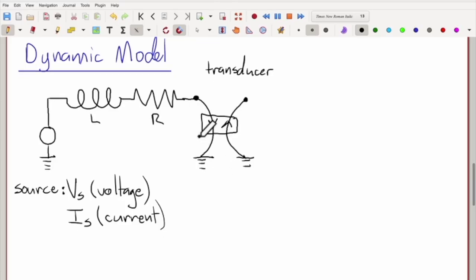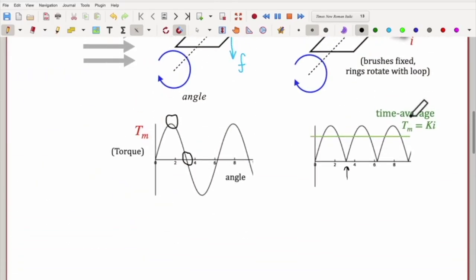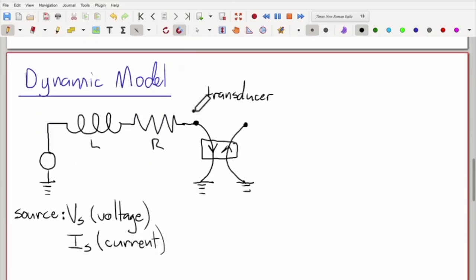And this transducer is this proportionality. Part of it is going to be this. The torque coming out of the coils is proportional to the current going in. So here's the current going in here. Let me make that red. And here is, I'm going to use the same color, the torque coming out. Okay, so I'm going to use this so-called mobility analogy where over here, this is the electrical domain.